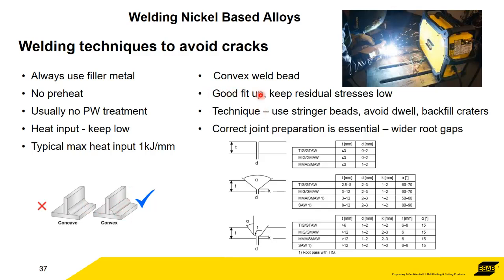Critically, a good fit up keeps the residual stresses low. If this thing's under strain, there just won't be enough strength in the weld to hold it together, and it will crack. In terms of your technique, use stringer beads. No weaving. Weaving increases the heat input.